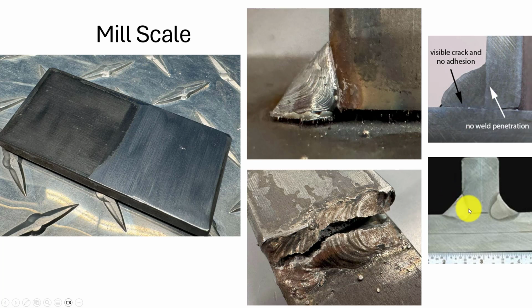Here's what we want. We want some fusion, some depth of fusion in this T-weld here. Now, you're saying this looks kind of like a crazy weld. I threw this up here because if we're looking at it, I can see that here we're welding along, and then it kind of changes here because look at the width of the puddle here. The welder that did this started going wider here, was narrower here, and it did break across the throat. Here's where they stopped, and when we stopped, there could be a crater, and that could become an issue with maybe potential breakage. So we may want to look at the broken part and see where we think it cracked and broke and started from.